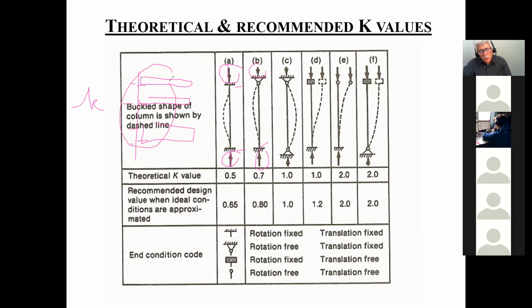It's very complicated. Well, not complicated. You've got to know what you're doing as an engineer. I recalculated the K value, and the other engineer that was working for whoever said that the K value was equal to 1.0, and I said no, the K value in this case was equal to 0.35, which drastically reduced the effects of the buckling, and therefore it drastically increased the resistance of the column. And of course, we didn't have to go and modify anything.